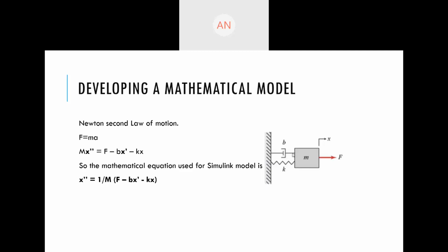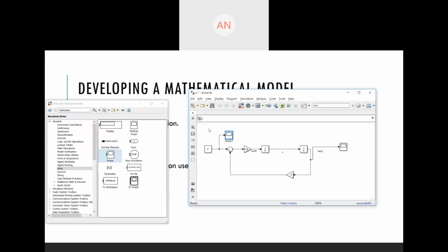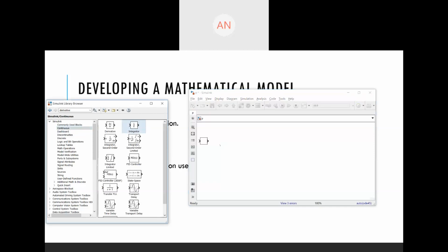Good. Now, let's get started to make the model. I'll call the library as well. Over here, first we'll delete the project 3. Deleted. Now let's get started. First, I'll need an integrator, so we'll go to continuous. We'll need integrator 1 and integrator 2. Right. Now we'll connect both of them.